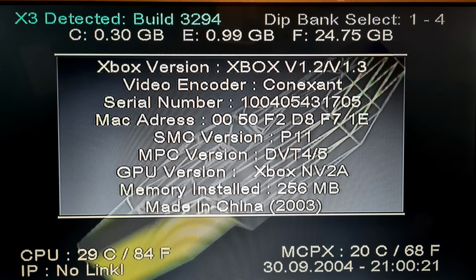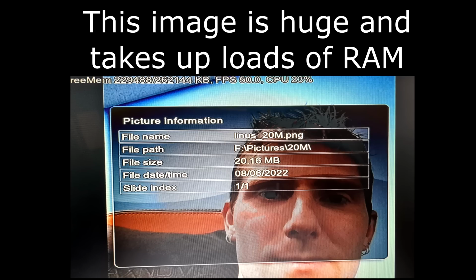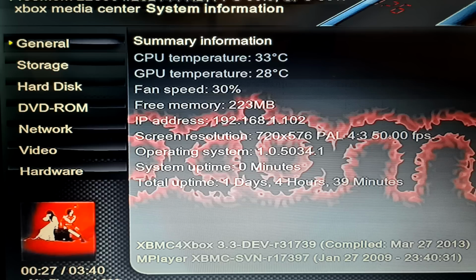So there's a look at the whole proof of concept. I went from really not knowing how DRAM was organized or refreshed or anything like this, to understanding how it's implemented in the Xbox, how to add more memory, understanding what parts are on the market and available, implementing a PCB, and getting it to work.